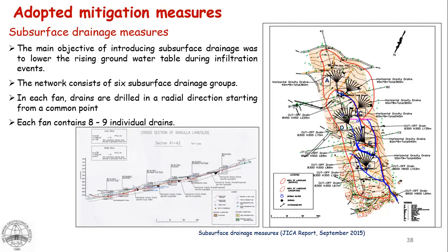It is necessary to cover that width to allow rapid dissipation of the pore pressure across it. These fan-type drains, as I mentioned before, are 40 to 60 meters long. There were 6 lines of fan drains from top to bottom, and you can see that here as well.